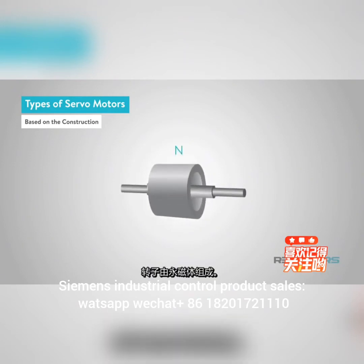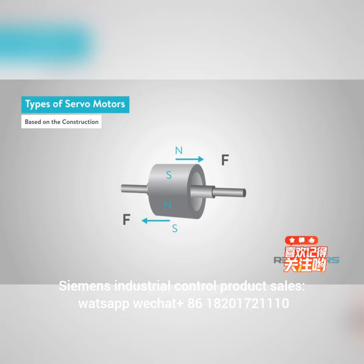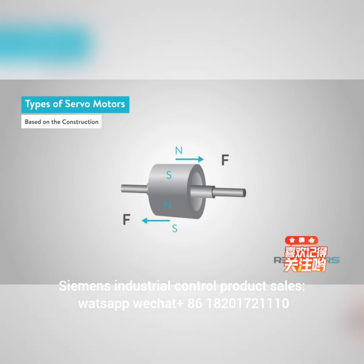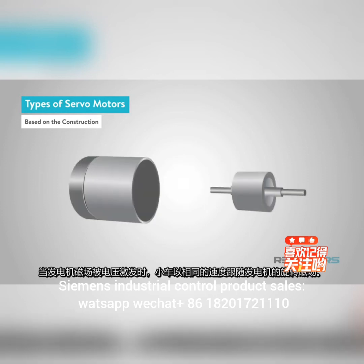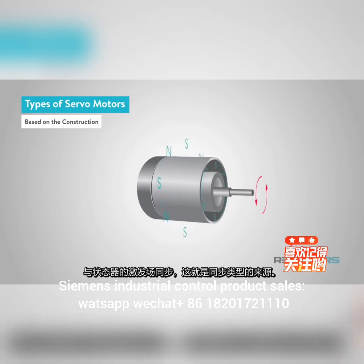The rotor consists of a permanent magnet, and this differs from the asynchronous induction type rotor in that the current in the rotor is induced by electromagnetism, and therefore these types are called brushless servo motors. When the stator field is excited with voltage, the rotor follows the rotating magnetic field of the stator at the same speed, or synchronized with the excited field of the stator.